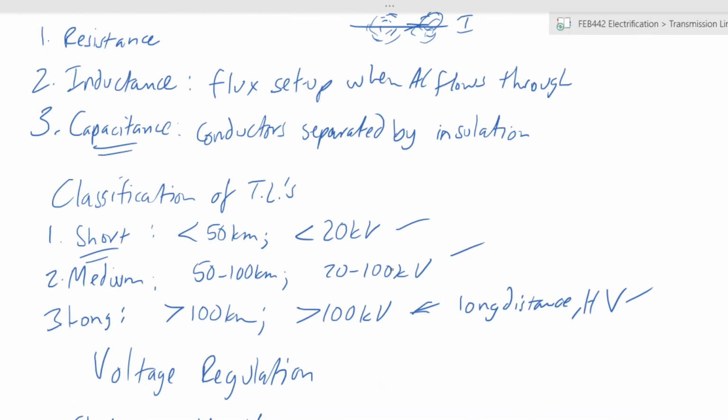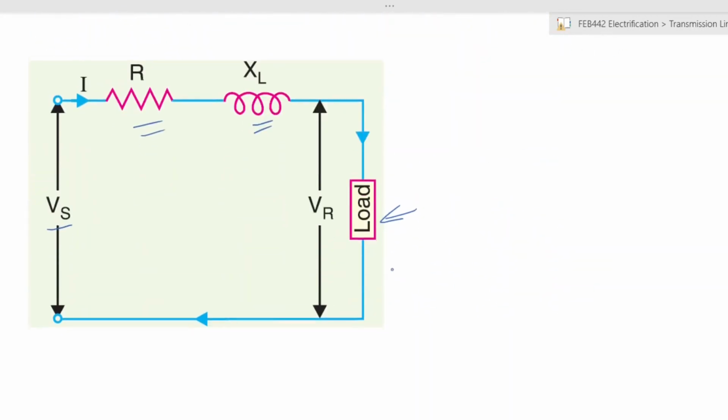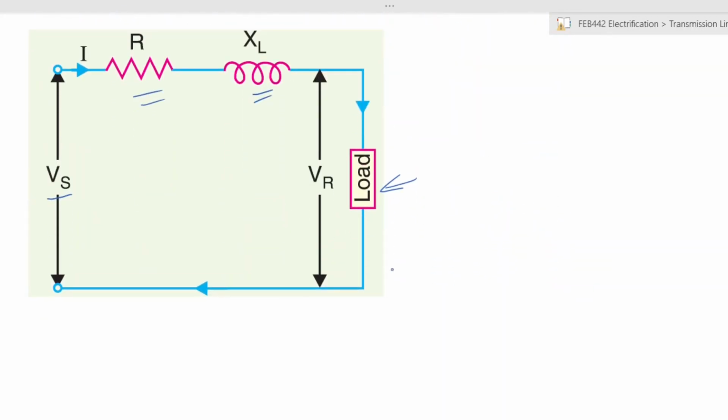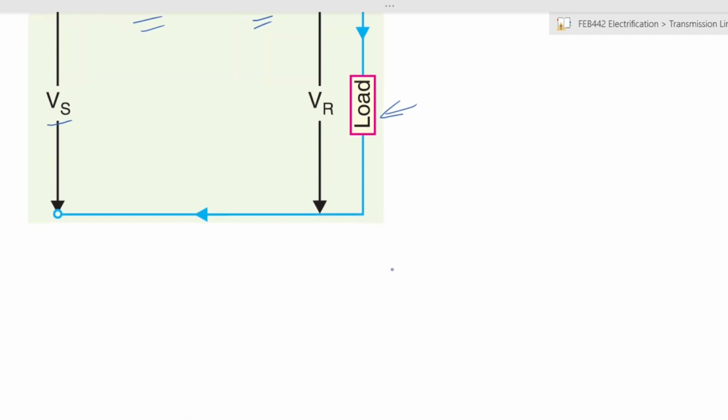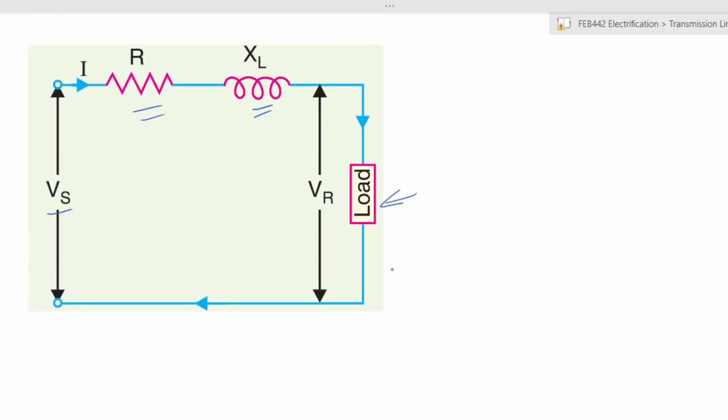Now, for purposes of our discussions, we'll be looking at short transmission lines. In the case of short transmission lines, the effects of capacitance are quite low, to the point of being negligible. So let's look at lines as being short, and see how we can describe them. At the receiving end, you have your current I. The same current flows all the way through the circuit. However, you have a voltage at the sending end, and a certain voltage drop due to the transmission line itself.